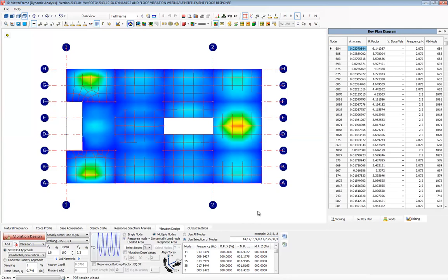What this basically means is that very quickly we can determine critical areas in our structure, and it's generally relatively safe to assume that the worst response factor at the critical areas will be caused by vibration at that area. So it's a fast shortcut to determining the critical areas, I suppose.